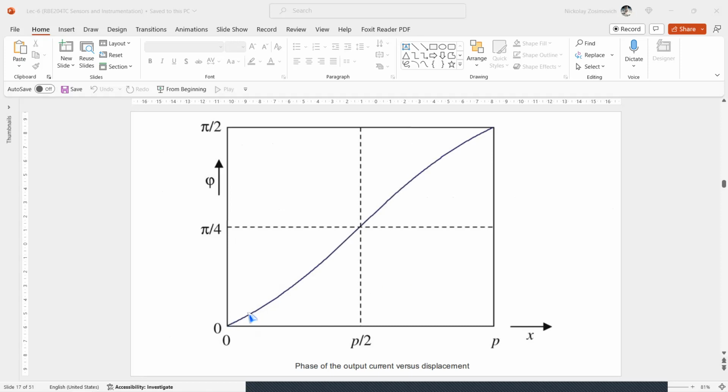We can see here in this diagram, it is generally linear in the middle part, but nonlinear in the initial and final parts. Guard fields cause further deviations from linearity, but even with guarding, the relation is essentially nonlinear. We can see this from the corner effect on both sides. However, by modifying the electrode shape, it is possible to get an almost linear relationship.